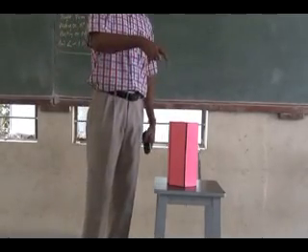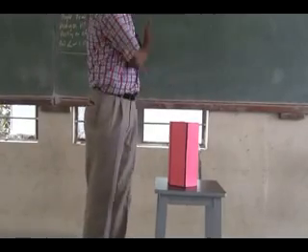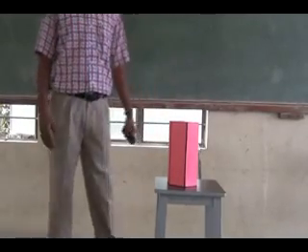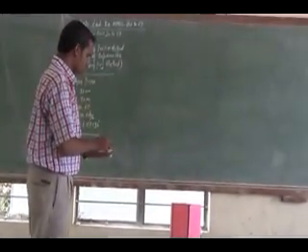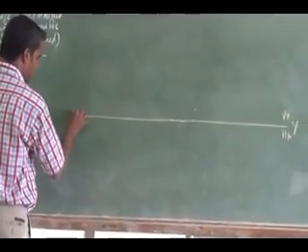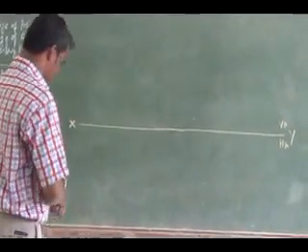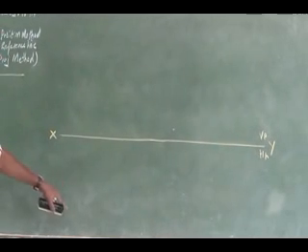Now I can clearly draw the true shape of the base on HP and I can draw the front view. Then I can tilt the front view to 30 degree inclination. Now you can draw the true shape of the hexagon on HP.